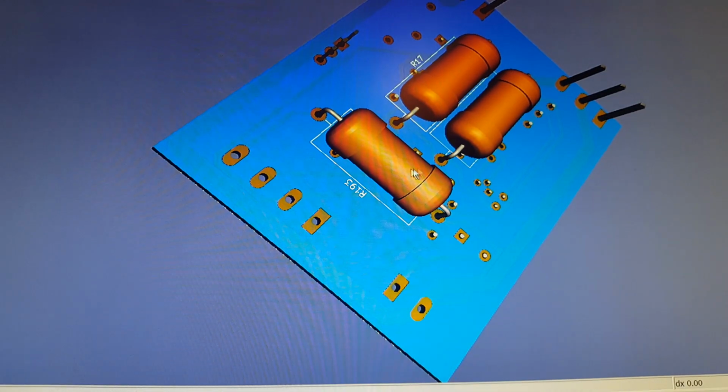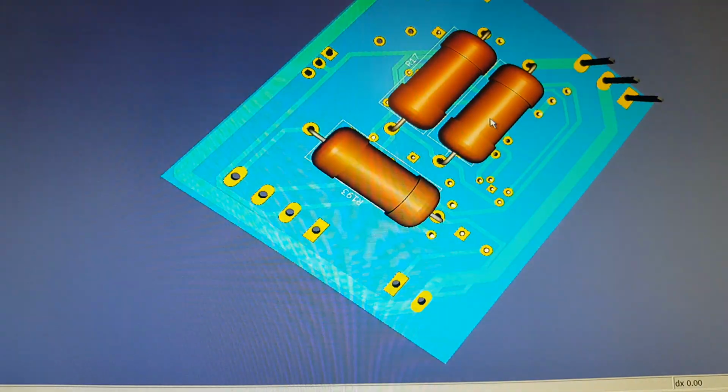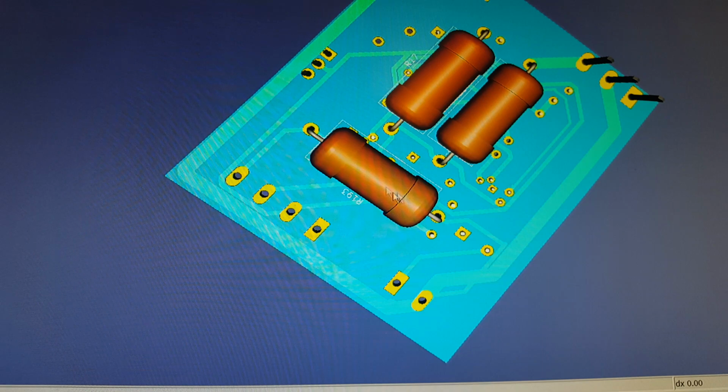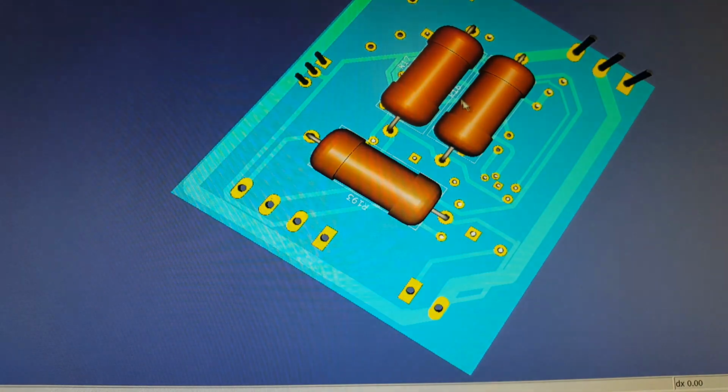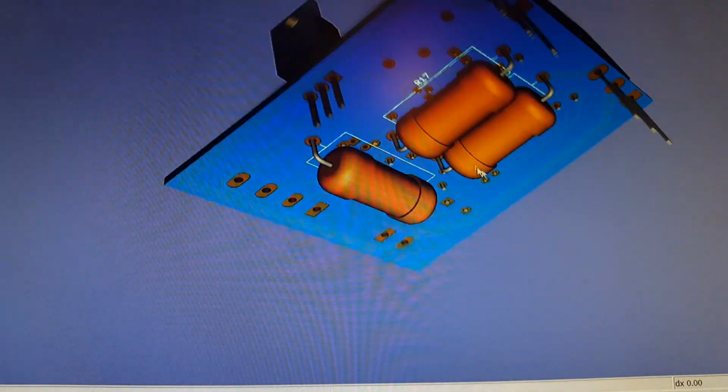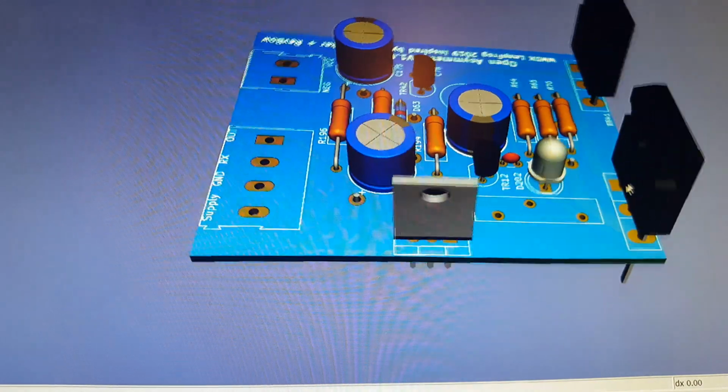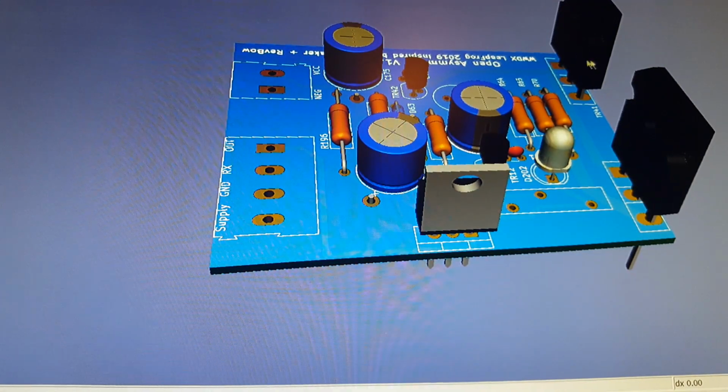R193 could be omitted. I've done it myself. I've omitted that before. It does help though to get some of that DC across without putting all the stress on the regulators. And then these two here are 0.1, just to kind of help balance these two guys out.